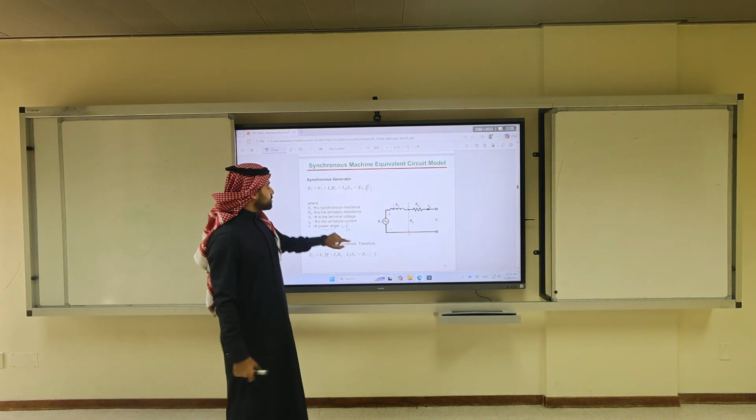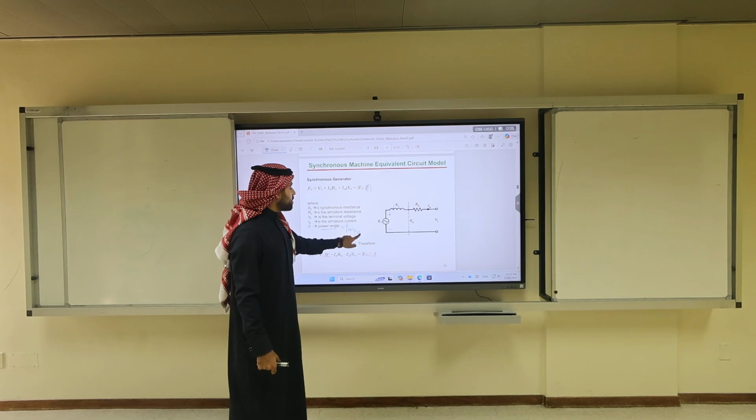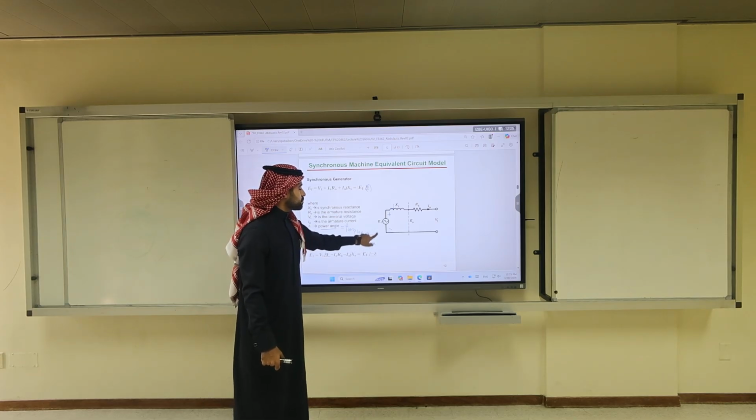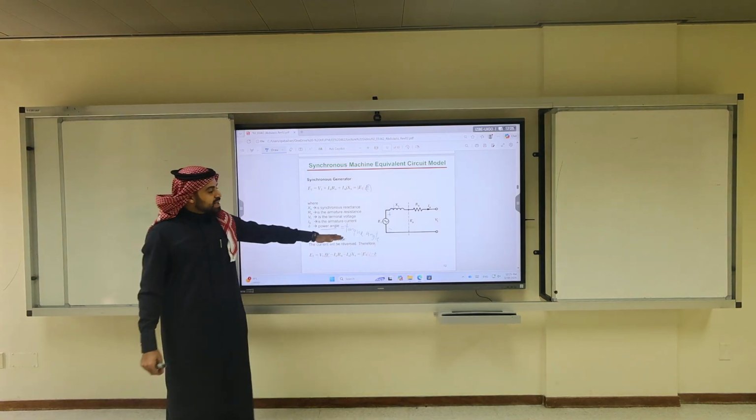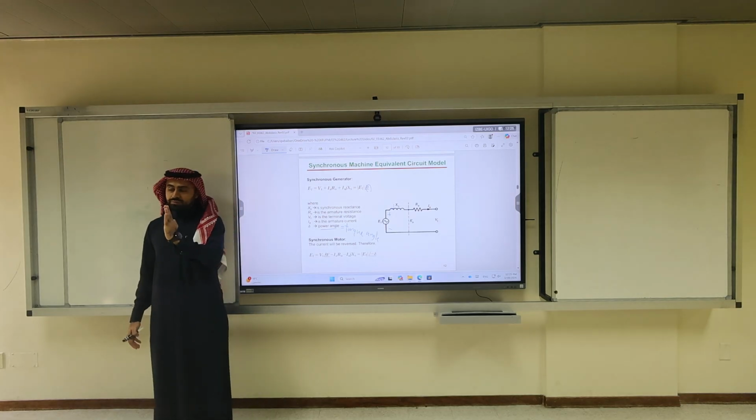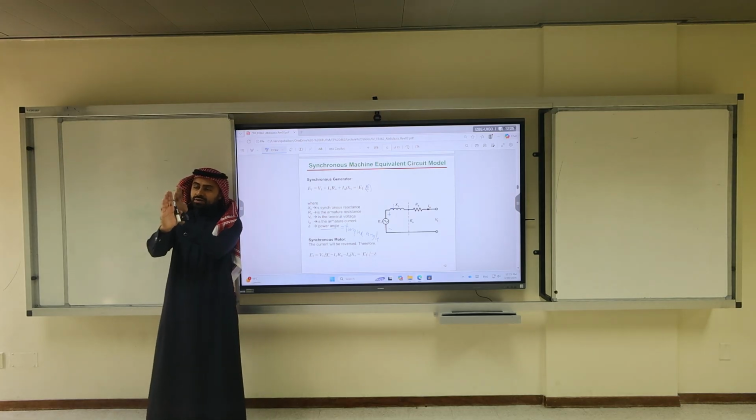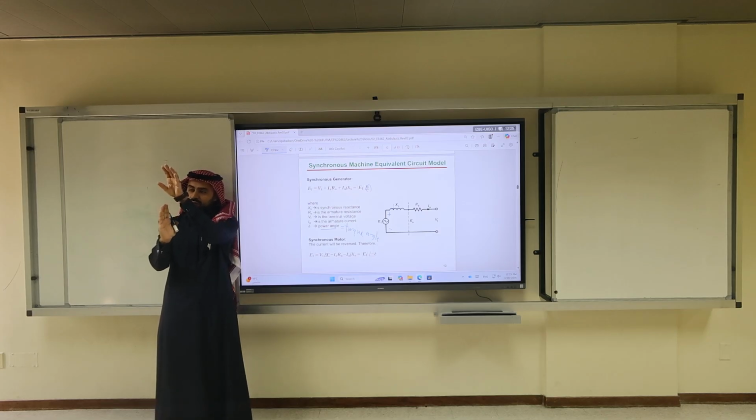This is the power angle. Sometimes we call it what? The torque angle. Basically, this angle is the electrical angle of how the rotor south pole deviates away from the stator north pole. If they are in line, you're going to induce the voltage in phase.